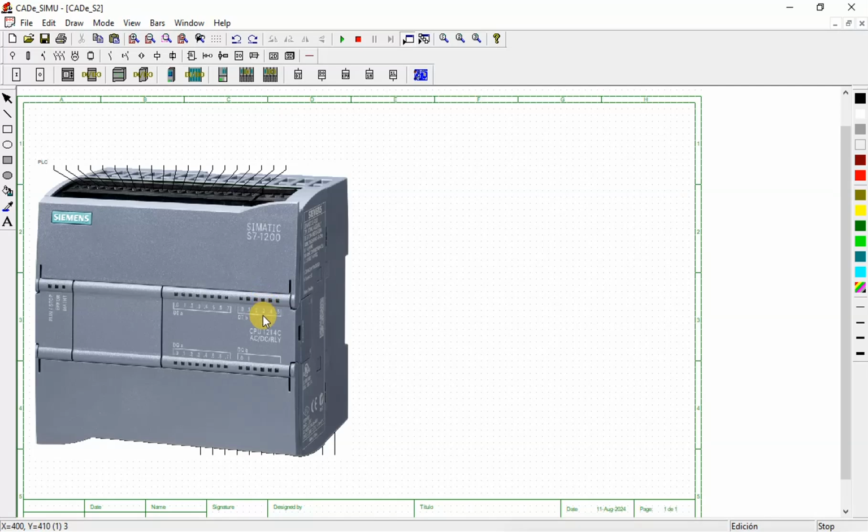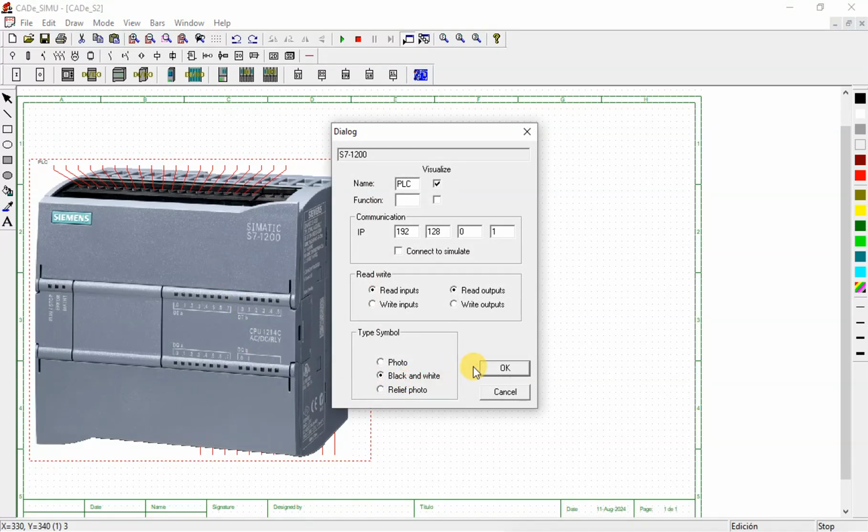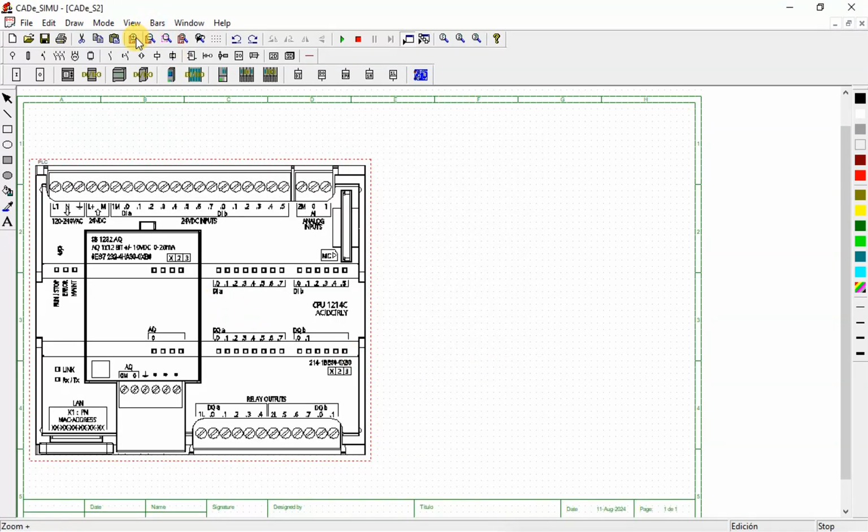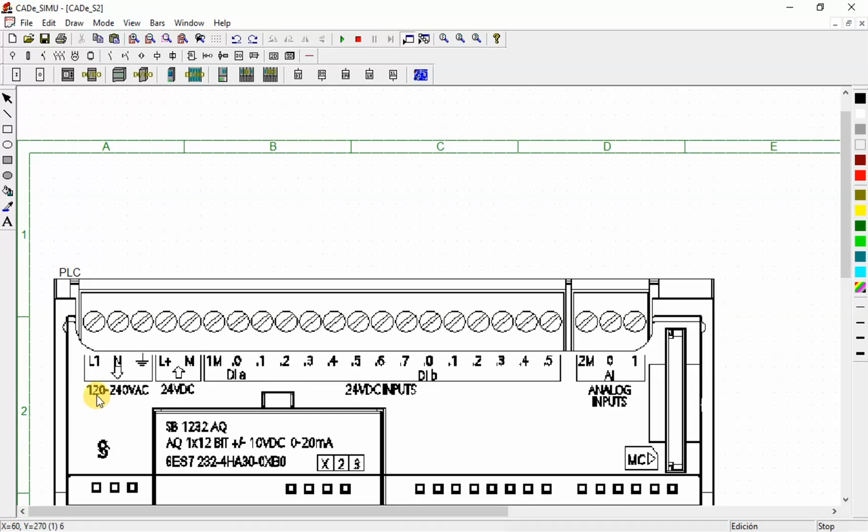Now before I start, allow me to go through this PLC. When we look at this PLC here, we have different pins. Let me have the internal view. We have these pins here, 120 to 240 volts. So we have live and neutral. This one is earth, which means we feed here live, here neutral, here earth. Then when you power it on, our PLC gives us 24 volts. This is live, this is neutral.